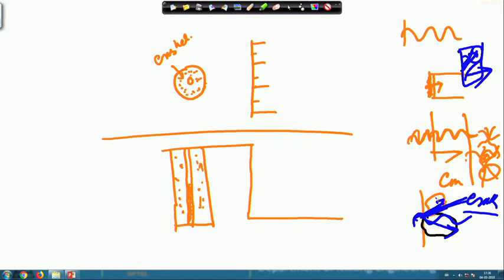If the heterogeneity of rock is there, shear will occur on that contact position and new cracks will be generated. So, by that way rock fails under shear in this position because of the wave propagation. So, what will happen? There will be a zone where rock fails or cracks are initiated because of the shearing motions among the rock grains. So, this is called cracked zone.